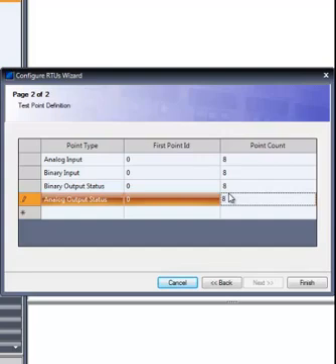In DNP3 task mode RTU simulation, a control request issued to a non-configured point will be rejected with an appropriate status code. Control output states and values are copied to the associated binary or analog input status point. For any other protocol, all controls are always accepted.